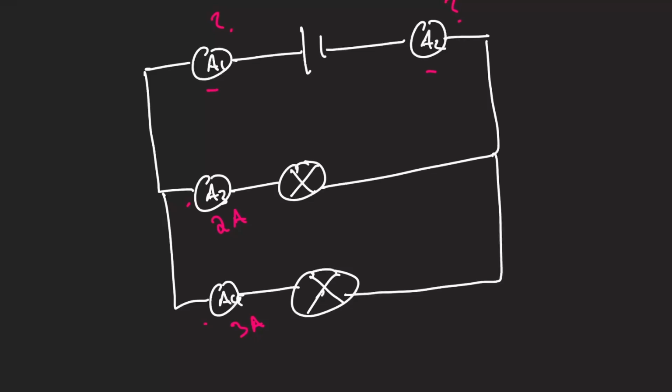So hopefully it again should be fairly simple if you just remember your rules in a parallel circuit. In a parallel circuit, remember the current is going to be split between the branches. And so your current will start off over here, it'll be split over here, and then it will flow back over here, and both of those branches will rejoin. What you then need to know is that the total current will be equal to the current in those separate branches. And at the beginning and at the end, when the current rejoins, it's the same, so you'll just add those two together.